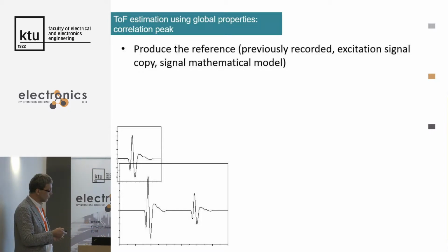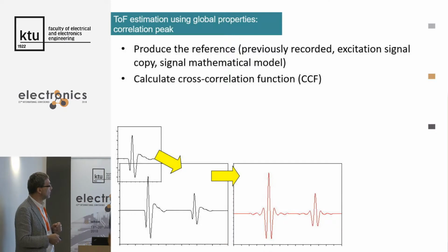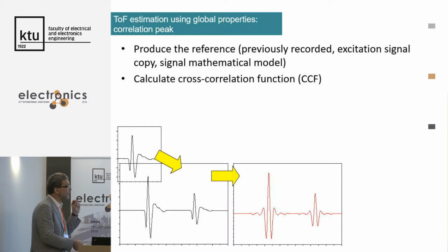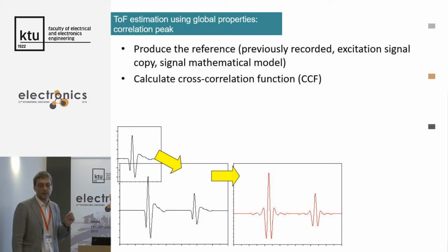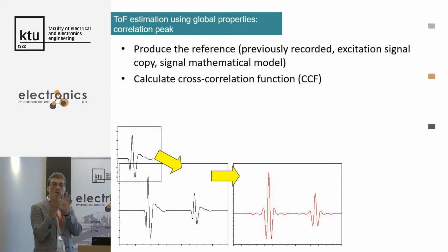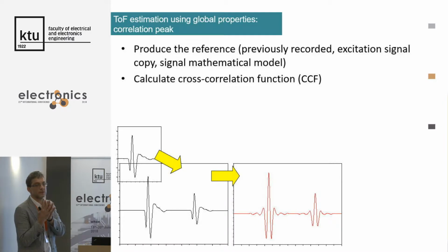So actually it is the cross correlation. Once we do the cross correlation, you see the result is somewhat different. But the essence is that now the peak contains all the energy of the signal, because correlation is multiplication: you multiply, shift, multiply, shift. If you have matched the signal and the copy of the transmitted signal, you get the signal squared, and signal squared and summation is the energy.